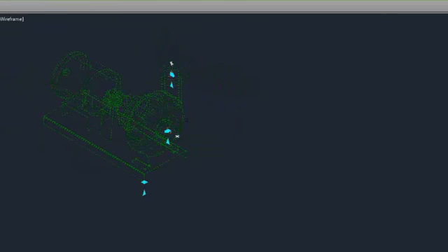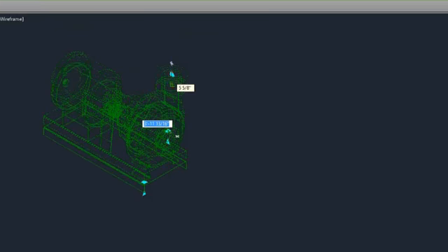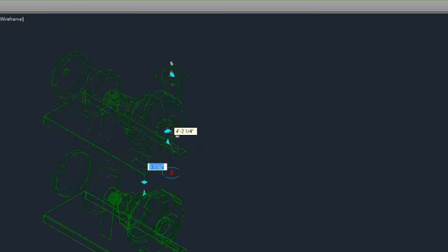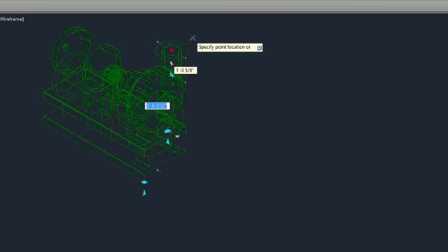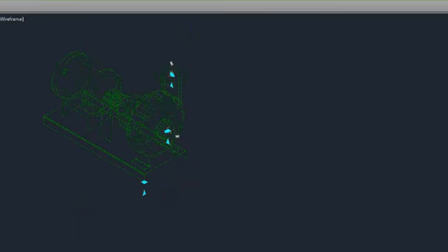The same is true for each connection on that multi-view part. We have a second connection up here that has the exact same functionality. You need to be careful though with the elevation grips. You can see that it knows that this connection is vertical and not horizontal, so it's only going to give you the relative move, versus the horizontal connector, which had 4 different types of moves: relative, top of pipe, bottom of pipe, and center of pipe.